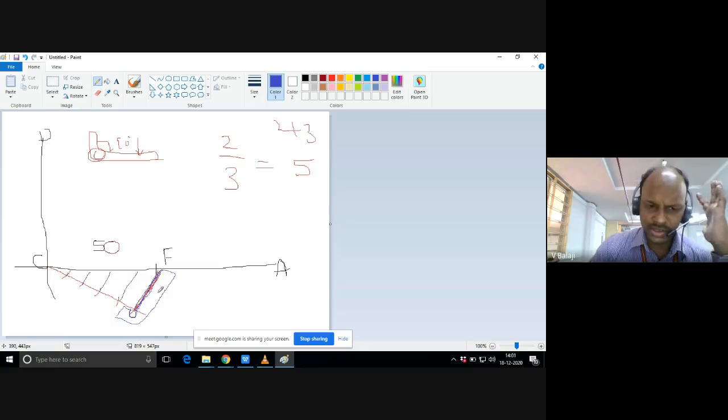Just match one of the mini drafter scales to this particular line, fifth arc to focus. We have joined one line with an ordinary scale. Match to that line and tighten the mini drafter. Gently move the drafter from arc to arc. Automatically you can create parallel lines. All these are parallel to each other, and also parallel to the first line we have created.